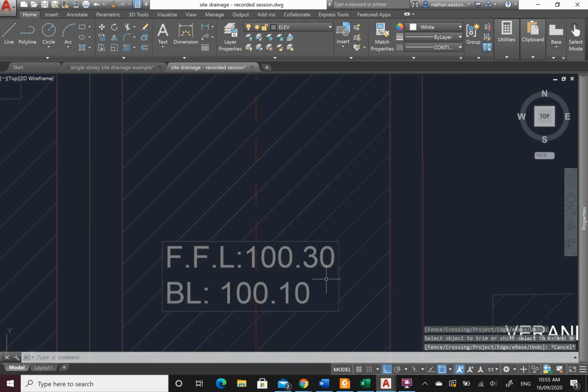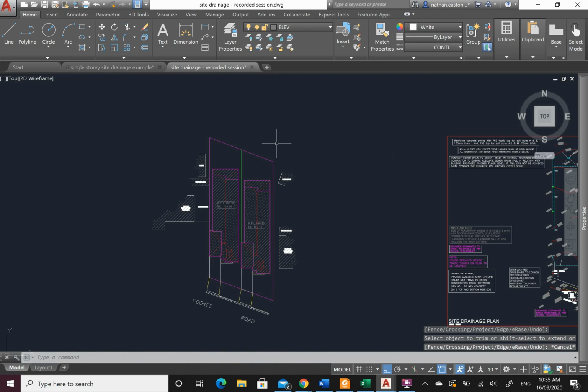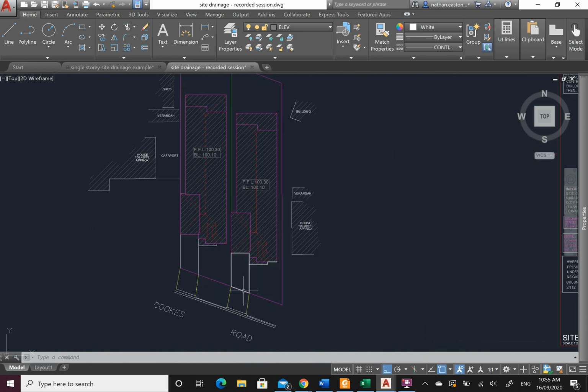Once you repeat it, the hatch will let us cut it. So this is the basics of our site plan. What we need to do is we've got a concrete perimeter we have to put around. So what they'll do is they'll pour the driveway and a meter perimeter around the outside of the house. The reason for that is this concrete falls away from the dwelling, so there's no water that pools or sits next to the house.